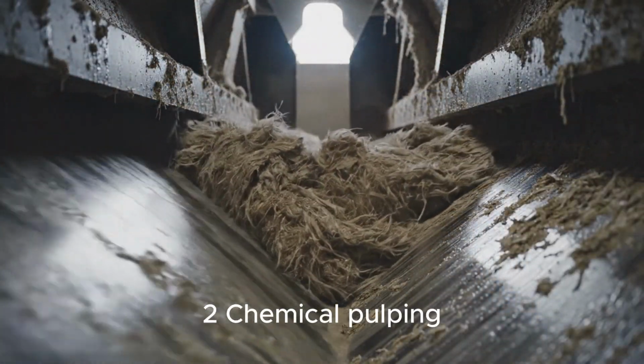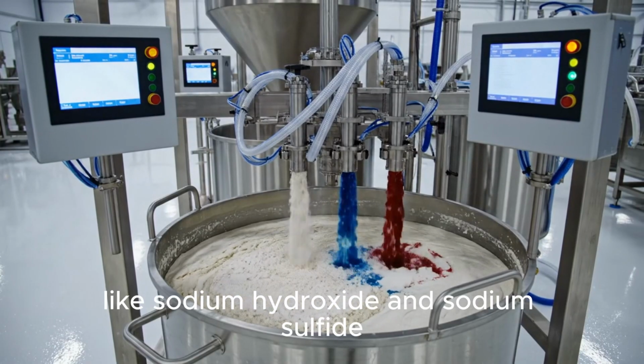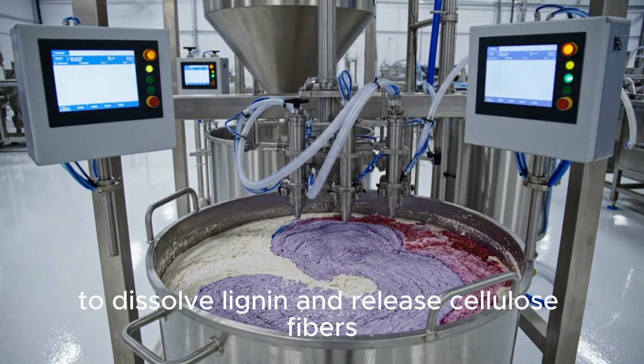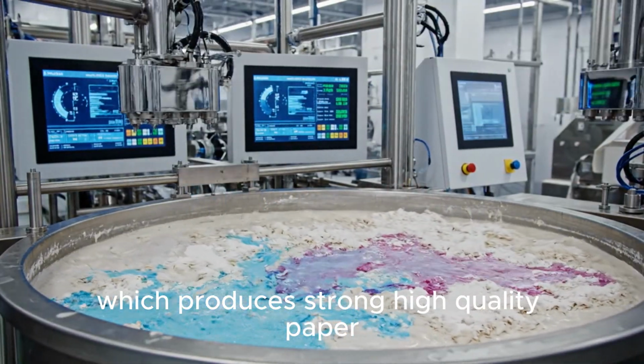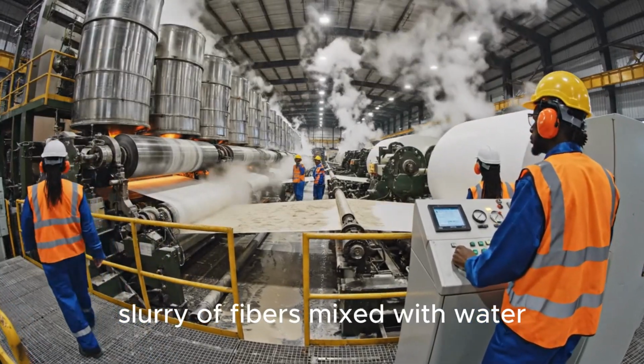2. Chemical pulping. Chemical pulping uses chemicals like sodium hydroxide and sodium sulfide to dissolve lignin and release cellulose fibers. The most common chemical process is the Kraft process, which produces strong, high-quality paper. The resulting pulp looks like a thick slurry of fibers mixed with water.